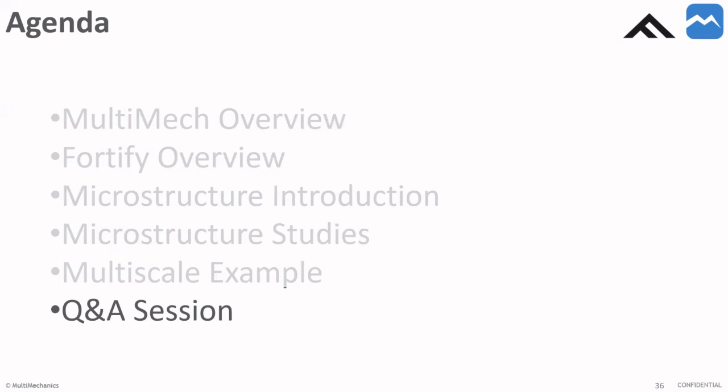Yeah, definitely correct. One thing to add: Hayden talked a little bit about importing custom meshes early on during the GUI demonstration. Essentially you can take really any mesher or even CAD program and create your own custom meshes and your own custom RVEs. That's been our approach as far as exploring the impact of fibers crossing RVE boundaries. And the MultiMech GUI is very receptive to those custom RVEs.